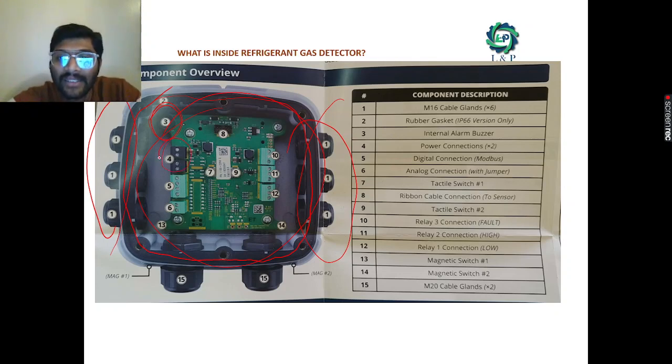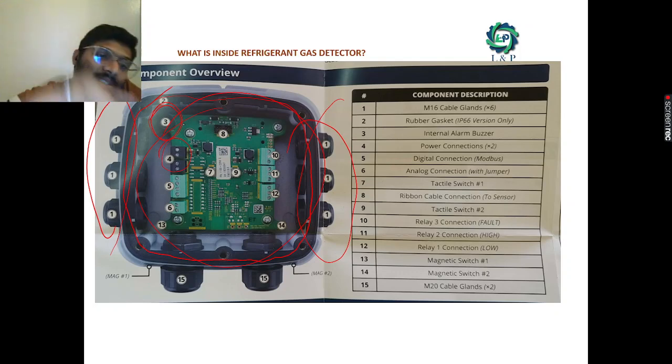As I told earlier, if there are multiple gas detectors, you want to take them in a Modbus communication loop. In order to loop, we need terminals, that is RX, TX, and grounding signals. For that, most importantly, you can use this terminal.